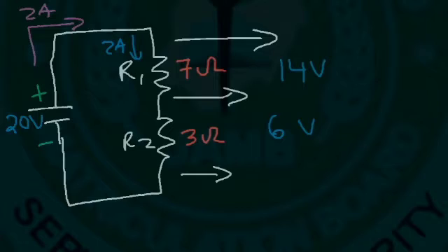Remember, the battery delivers energy, and the resistors absorb energy. Now, I've seen different sign conventions when you're deciding which ones are positive, which ones are negative. But regardless of which way you do it, the sum will always be 0. Now let's say at this point the voltage is 0. That means at the top the voltage must be 20, since across the battery the potential difference is 20. The positive side is the side of the higher voltage.